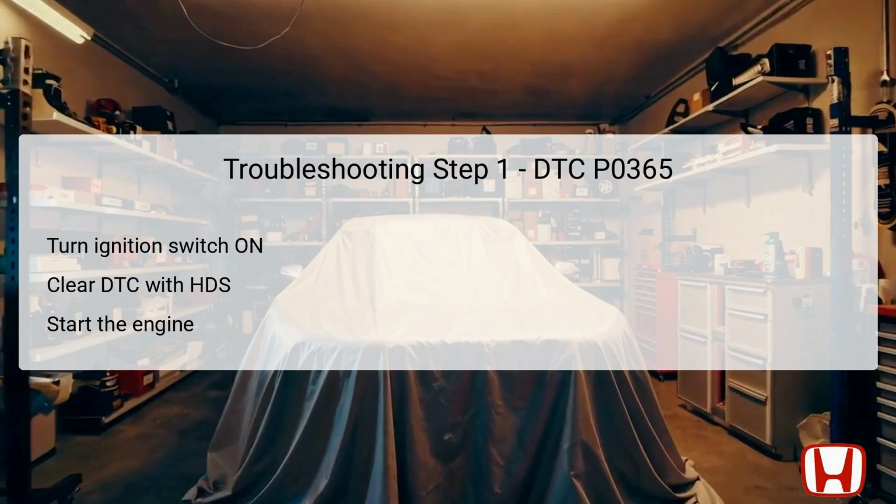Once the DTC has been cleared, you should start the engine to determine if the fault reoccurs. This initial step is significant as it allows you to ascertain whether the error is active or has resolved itself, laying the groundwork for further diagnostics. It's essential to have an accurate starting point to identify persistent issues effectively.